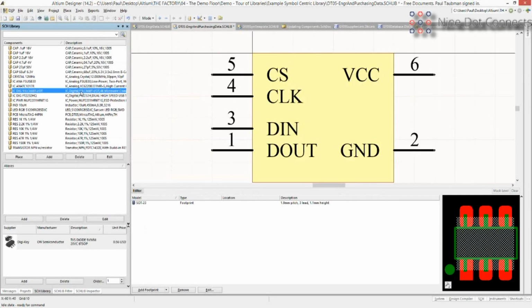Now, last week I went into a lot of detail about that, but when I took this library, I took the DT05 project from Altium, and I said, okay, I'm going to extract out these parts. And when I did it, I had to clean these up, and I spent a lot of time doing it. But the reason I wanted to do that was to emphasize that once I clean them up, this is very organized, and I can read this very quickly, and I can see what these components are doing. And that's why it's really important to come up with your own nomenclature for the description.